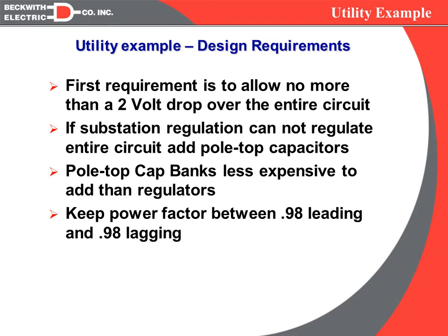We don't mind going leading because we do have these 20 or 40 MVA power transformers in each distribution substation that do have inductive impedance. And if we want to be VAR neutral to the transmission grid, then we need to be slightly leading at the load side of the distribution buses on these transformers so that the additional capacitance can counteract the inductance of these transformers. And it's very beneficial to be VAR neutral to the transmission grid because it's much more expensive to add VARs at the transmission side for voltage support than it is at the distribution level.